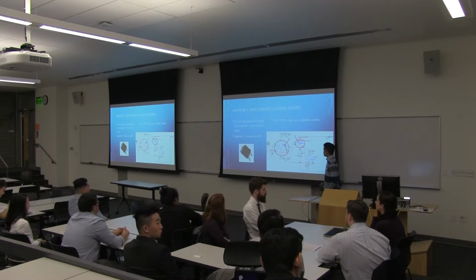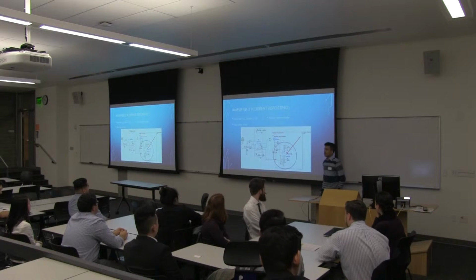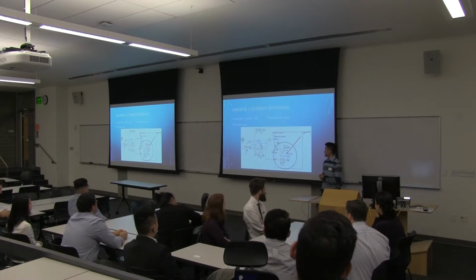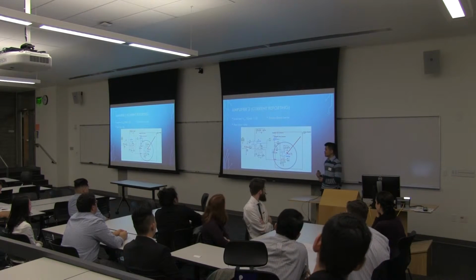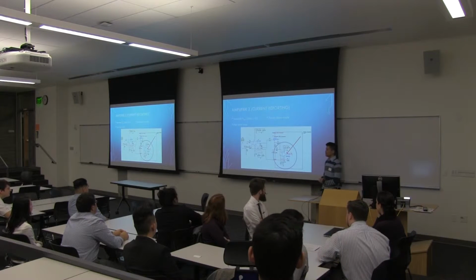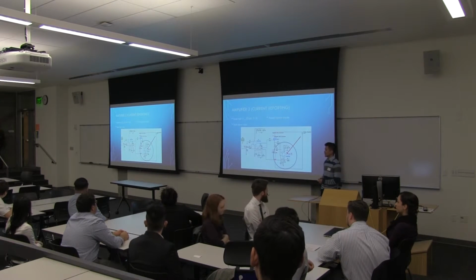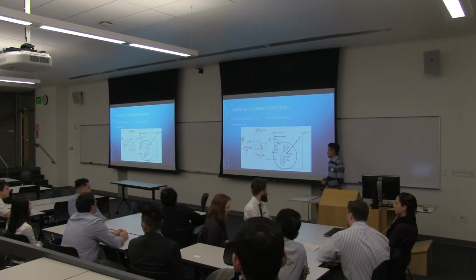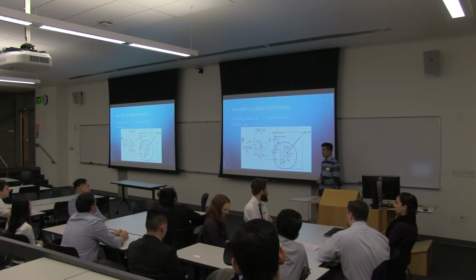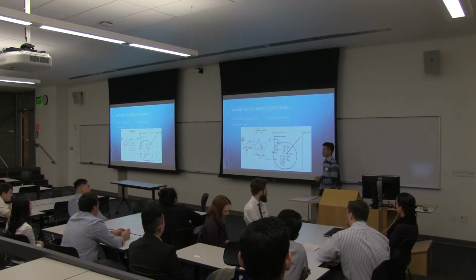Hi. So another main component we use for our design is an inverting amplifier. We call it amplifier 2. It is used to accurately report design output current. It has a gain of -5 to be able to invert and amplify small negative current to 5 times greater positive current.